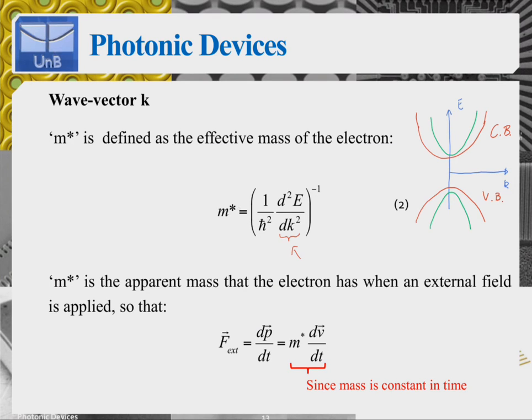The effective mass is proportional to the inverse of this, and therefore, since the second order derivative is larger for the green curve, the mass is going to be smaller. So the electrons corresponding to this conduction band in green would have a smaller mass and would therefore be lighter and move faster through the lattice if subjected to an electric field. Okay, so this kind of information can be obtained from the band structure as well.